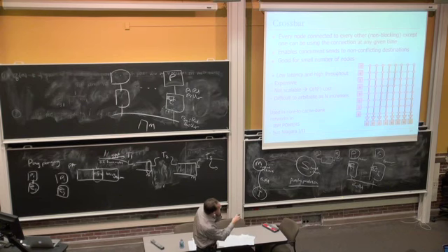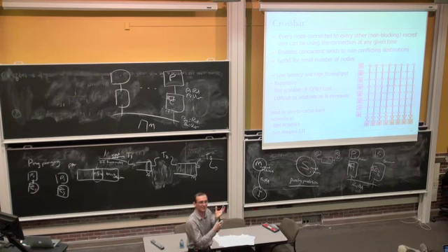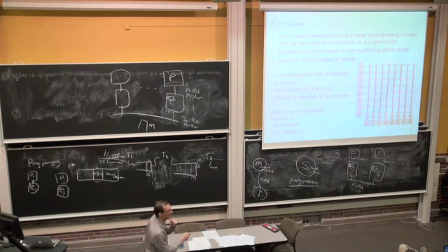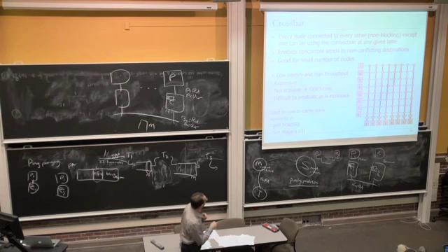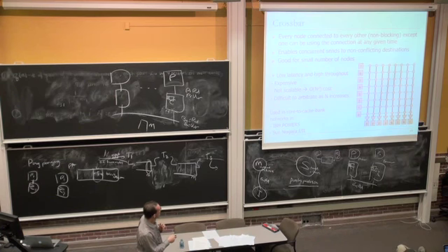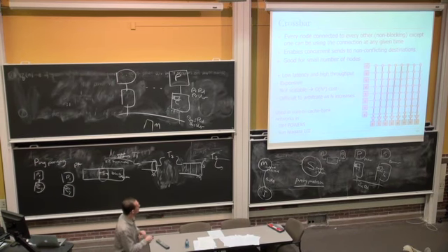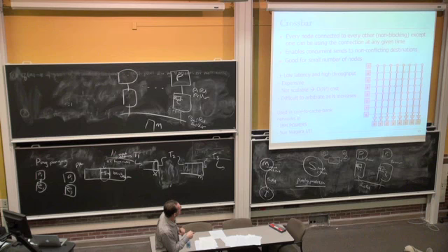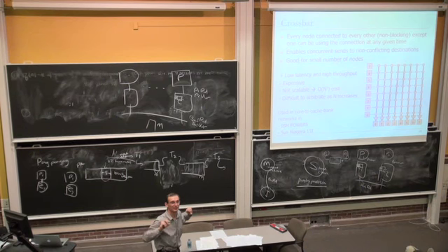Okay, so it is difficult to arbitrate as n increases. And again, that makes things slower, right? Let's say you want to put 10,000 of these here and 10,000 of these here, essentially you have a bus, right? Or some arbitration mechanism is needed for the conflicting destination. But for small-scale systems, this has been used. This is used in some multi-core processors. We'll take a look at that. Sun Niagara 1, 2, IBM Power 5, and I think the later IBM processors also have this. They use it to connect the cores to cache banks, the shared cache banks.